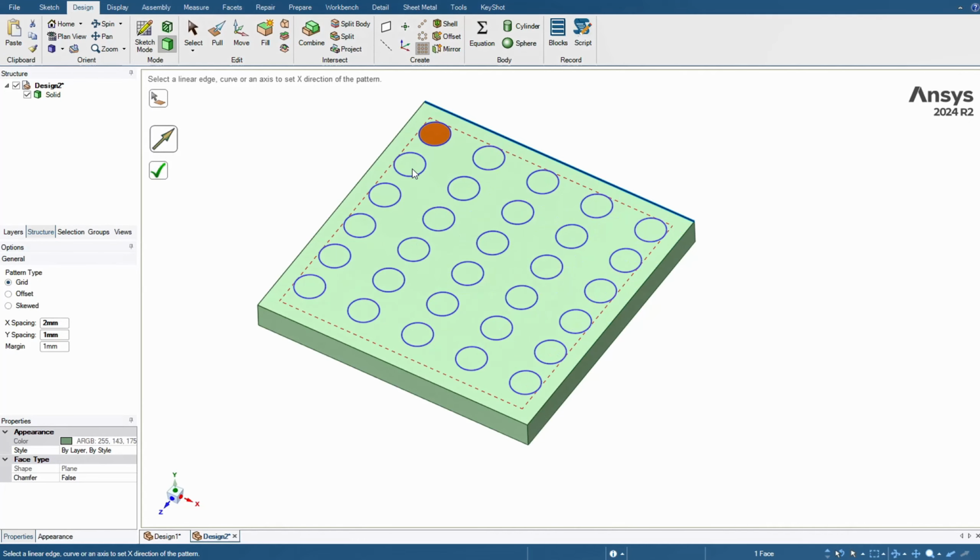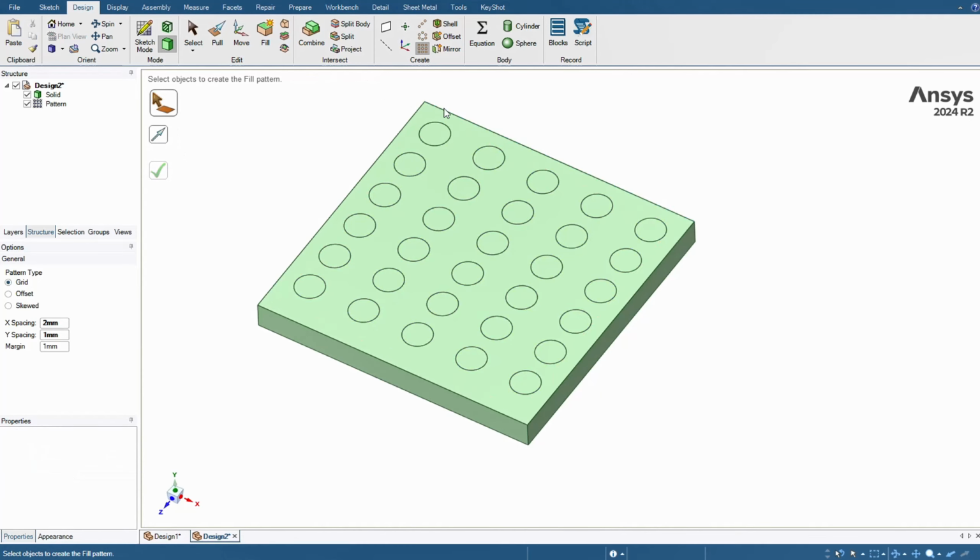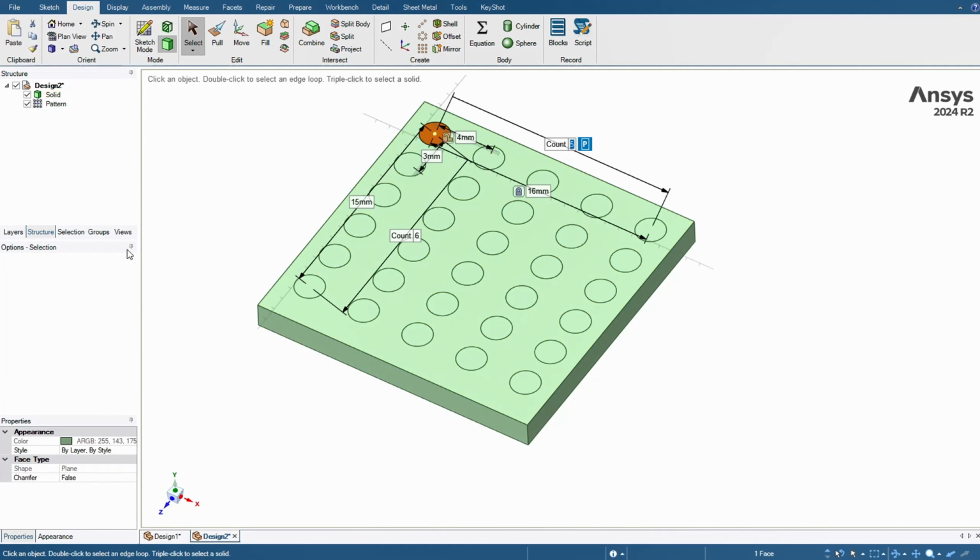As you can see, I used this command to create the 2D sketch of the pins. The key step now is to extrude these pins using pull. To select all the circles, you don't need to pick them one by one while holding Control. Just open the selection panel, choose Faces with same area, and then extrude them all with pull.